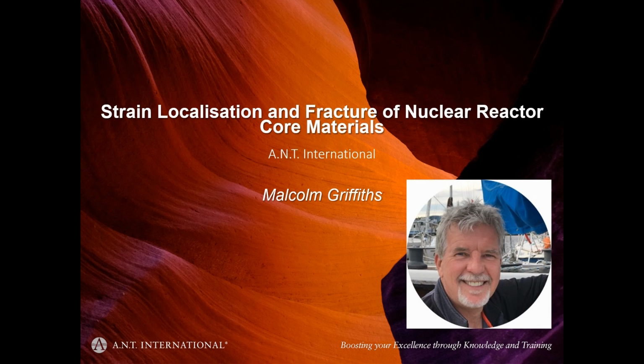However, many of my colleagues and certainly the engineering groups believed that there was another explanation for the degradation, and when an assessment document was written, it was written in terms of the failure mechanism for these components being the interaction of slip bands with grain boundaries. And that was kind of a catch-all, hand-waving explanation for which there was no evidence.